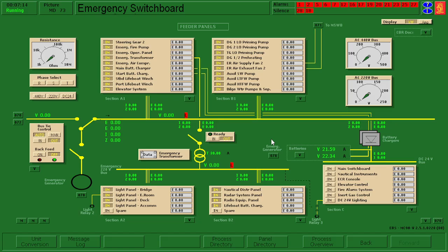You certainly couldn't do that with a turbine generator without a lot of preparation, hours and hours of preparations. Black starts are incredibly difficult things, but this is a ship. We've got diesel generators on here, and diesel generators are designed specifically with the black start in mind. So this is a perfectly okay thing to do.